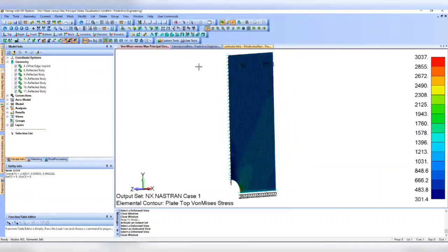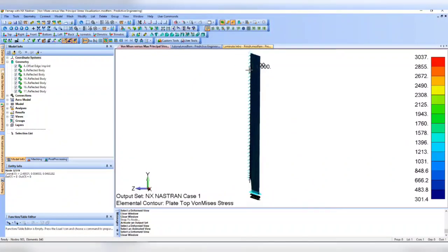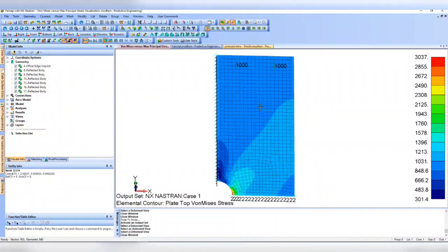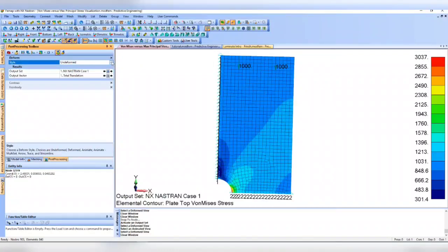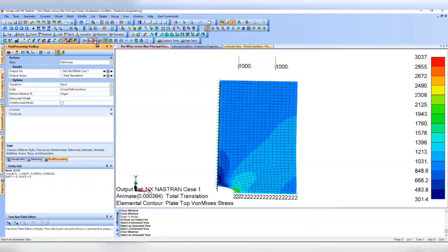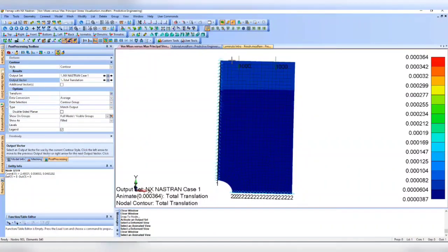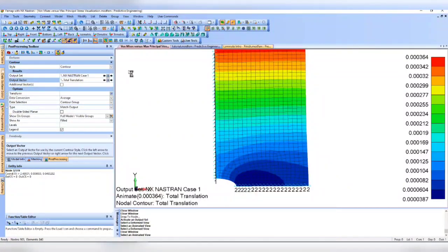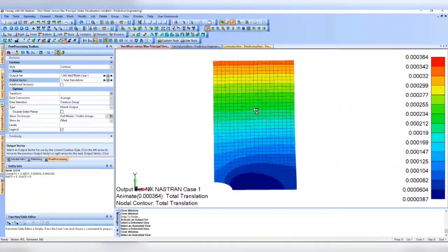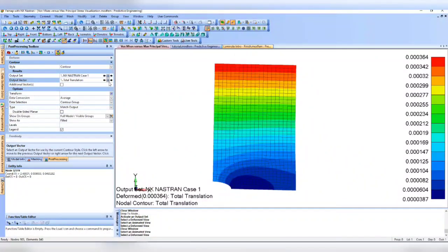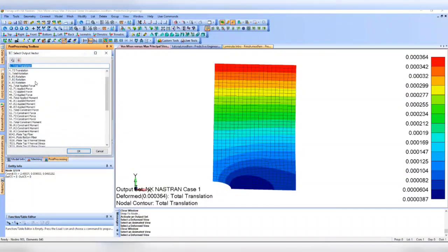All right. So in this case, I'm actually applying a compressive load. So you can see the green arrows, it's actually going towards the plate, not away from the plate. So it's compressive. And let's check the deformation. And you can see how it's deforming, right? That's nominal and it's compressing, all right? I'm gonna hide the forces now. So this is the deformed shape. And the question is, okay, let's view what the stress concentration levels are. So let's go to contour, plate.